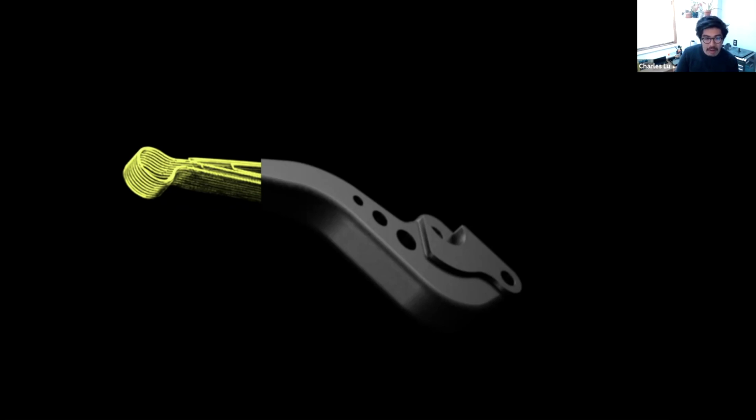It can be done, and the continuous fiber helps a lot. Your surface is still going to be that chopped material. So depending on how many shots you're trying to go for, you may see that it is not going to last as long as a tool steel die, but you can certainly use it in shaping. Yeah, I would not use it in any shearing operation.